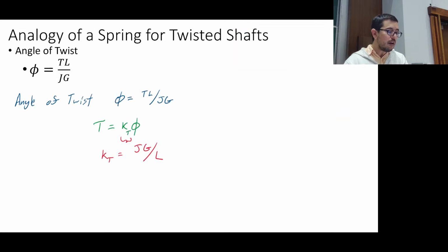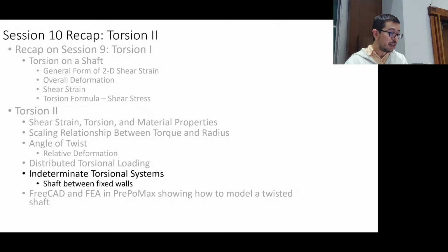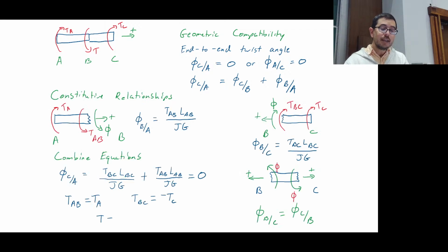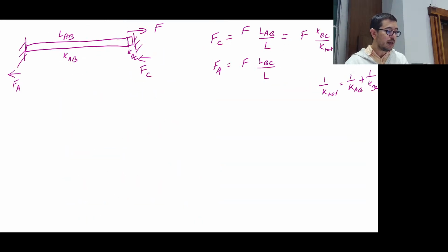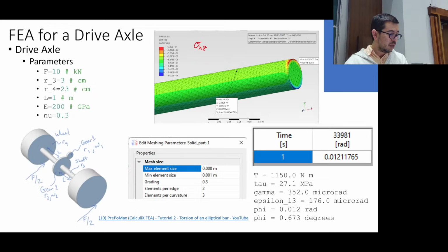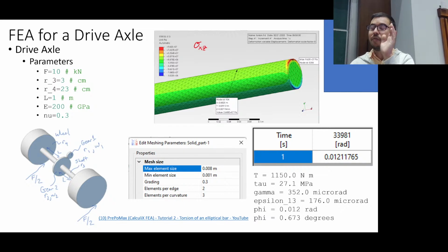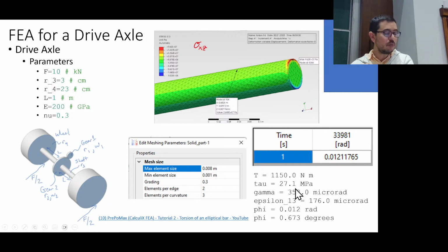There are some nuances that I'll talk about in the video between the shear strains that you calculate by hand and the tensorial strains that ParaView uses. So there's a factor of 2 between them, but that will come out in the videos. So, where is it? Oh, sorry, not 250, it's 10 to the 7th. It's like 25.6 megapascals. My bad. So that's 27.1 megapascals is what we calculate. So we're in the right ballpark.